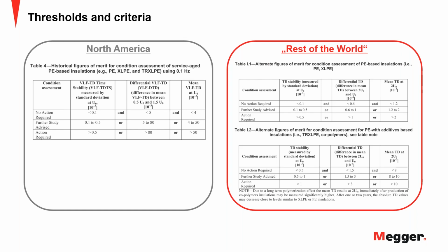I have to repeat this. You have to go beyond the numbers. The numbers are a starting point. They give you indication, inception voltage, extinction voltage, and then the activity that you measure. But you have to take into account more factors for proper decision making.